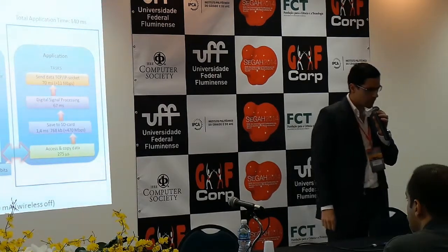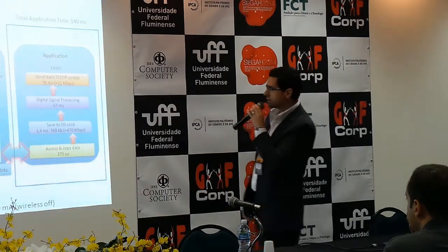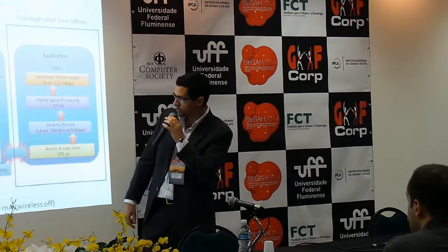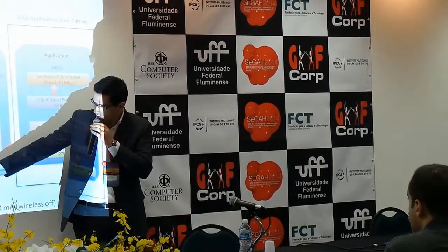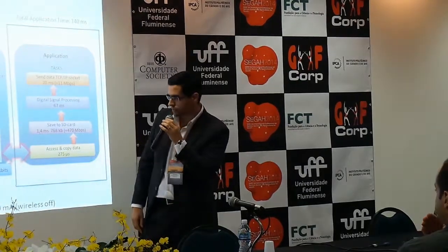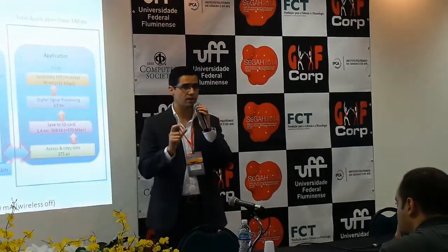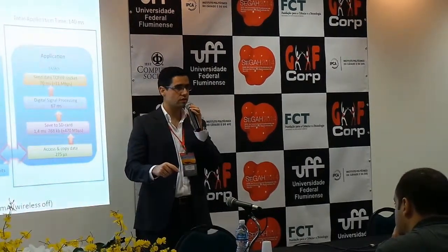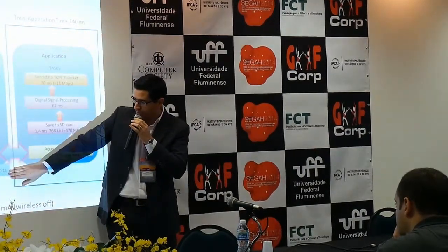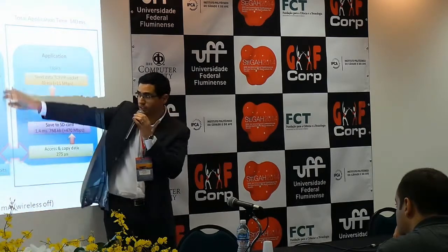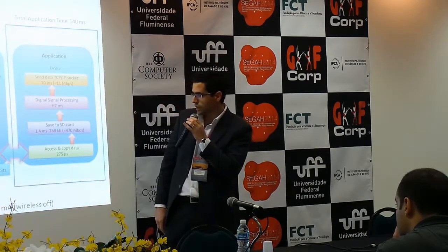Regarding performance of this test, it is working very well actually. You can see here the time that we spent to accomplish this task. For the actual acquisition of the samples, it's 427 microseconds for 768 bits, which is one sample of data, for the 32 channels times 24 bits. Then you acquire 1 second of data. That's the size of this buffer, 1 second of data, which takes